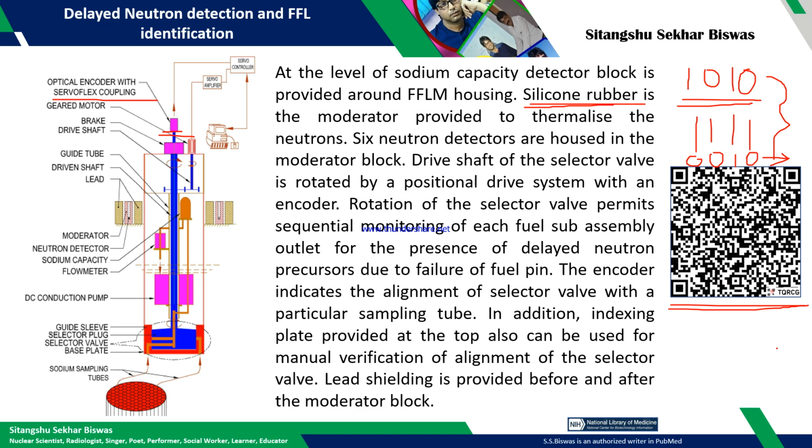We have made our own. I have designed our own SSI card in Modbus protocol that can be interfaced with any PLC or controller. I also explained in Unity Pro, the Schneider PLC, how the high speed counter card is configured to interface the SSI encoders.